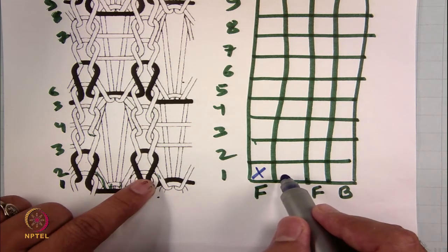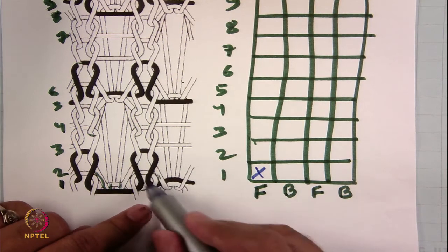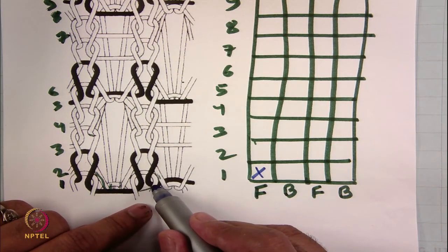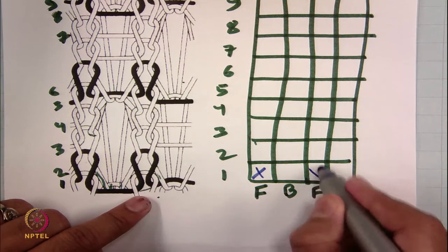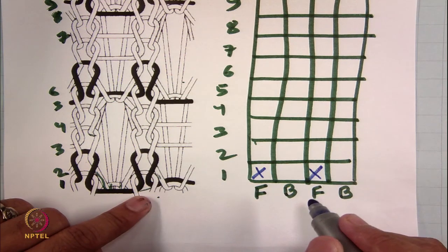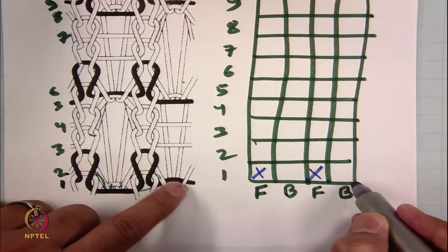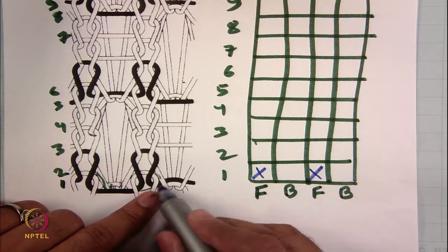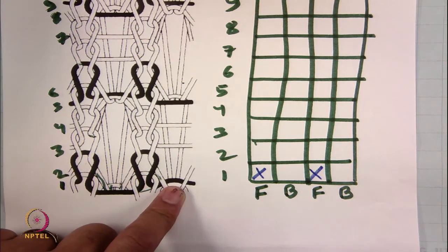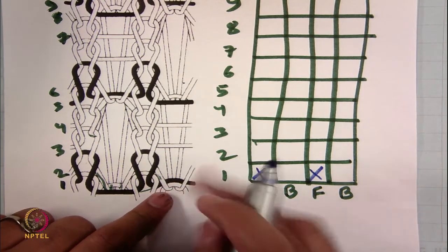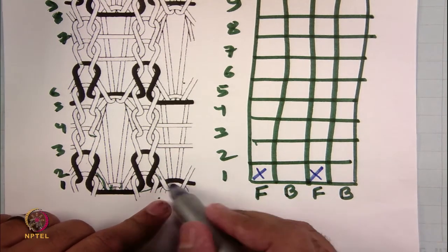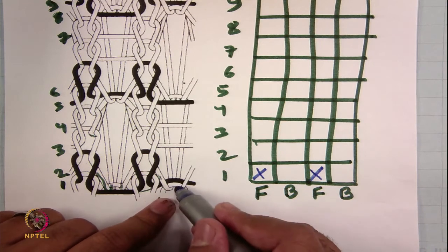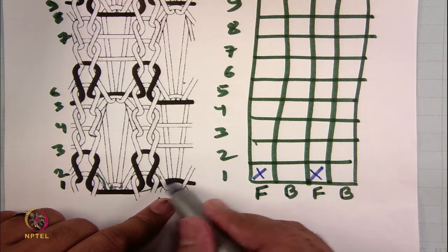Then if you go for the third loop of the first course, this is technical front, cross. Then if you go for the back bed needles, especially this one, here the yarn is towards the head side, and if you carefully observe the needle movement, especially at this point, it is catching 2 yarns. One is this white yarn and the other is this black yarn.